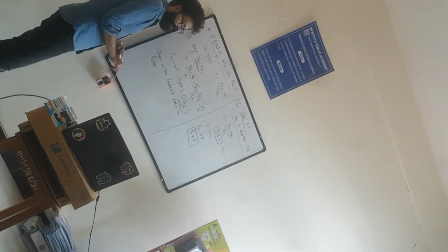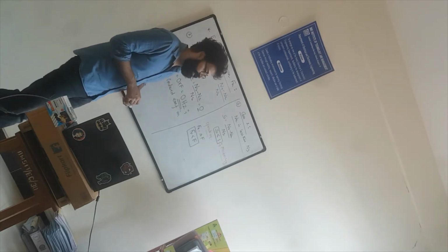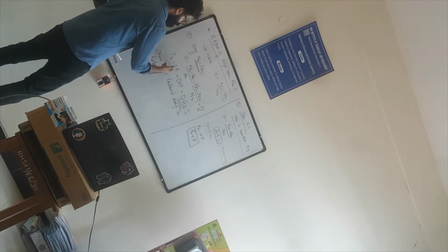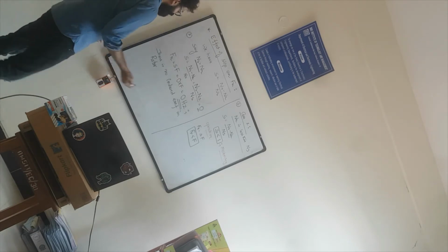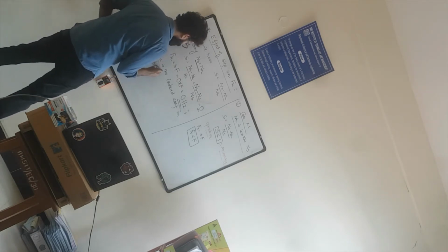You can say something like the signal is dead. And why is the signal dead? Because there is no relative speed. If there is no relative speed, the rotor frequency becomes 0, and 0 frequency means there is no EMF in the rotor.